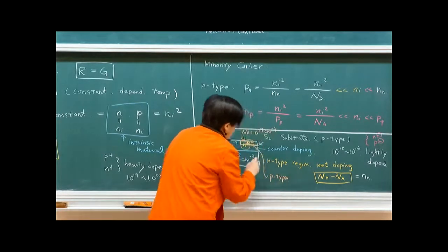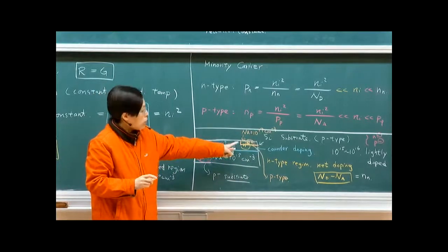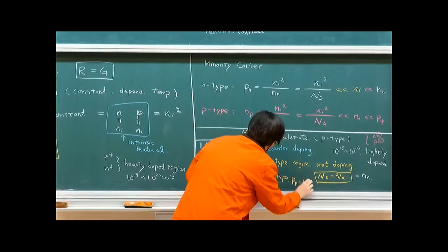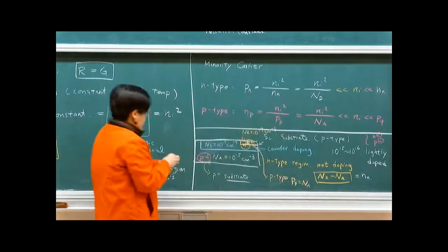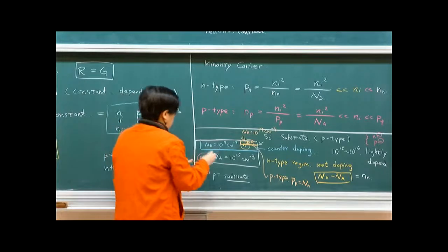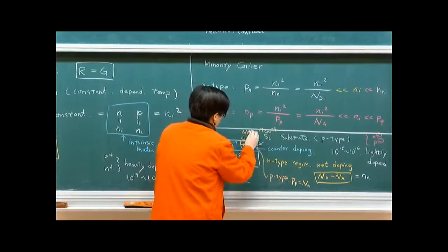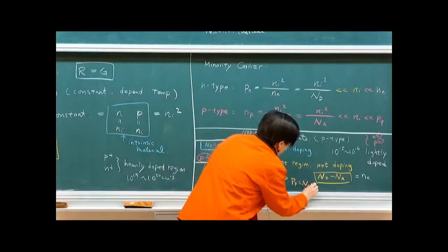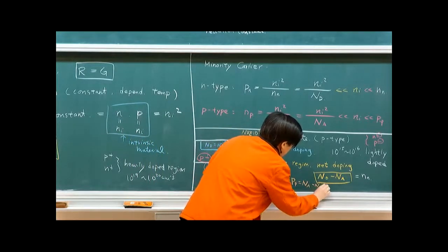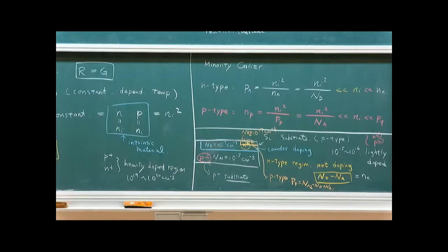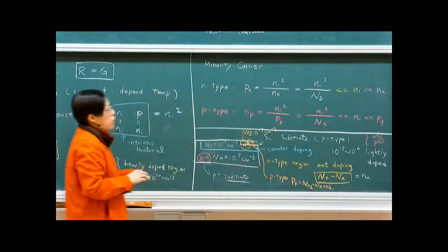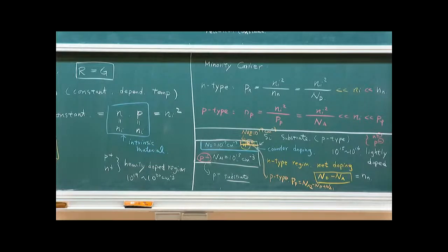So what we're concerned about is the amount of carrier concentration in this region. If I want to write a P-P, it will be NA, because I have two NAs, therefore I want to label it. This is NA1, this is NA2. Let me write it over. So for this region, it will be NA1 minus ND plus NA2. Okay? Is that clear? So you add all the acceptors minus all the donors when you want to get the final result. So you counter-dope it twice, right?